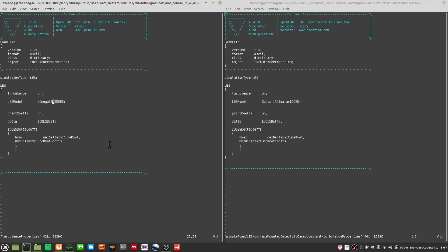One very important thing to remember is the Prandtl number. So the Prandtl number, I'm just going to set it at 0.9. PRT, this is the turbulent Prandtl number, very important. Okay, I'm going to set it at 0.9. Alright, so when you do this, it will set a uniform turbulent Prandtl number all in your fluid,